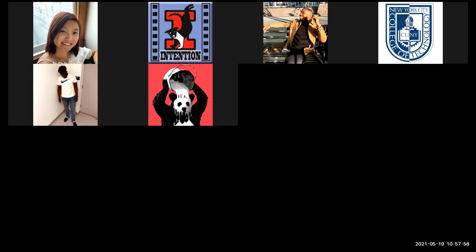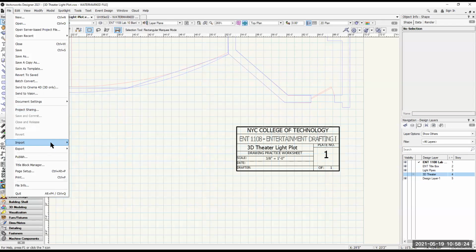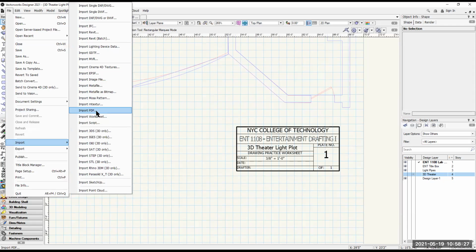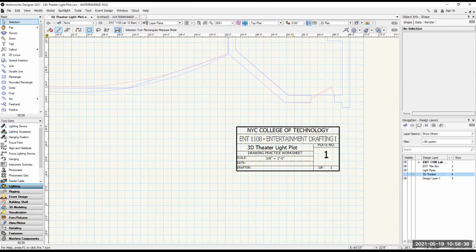The black box is a PDF, right? So I'm trying to insert that, but it's not working. Well, you have to import it. It's an import of the PDF. If you're going straight to Vectorworks, that's a different process. If you want to import a PDF in Vectorworks, that's file import. The PDF is down here because you could grab it right from there. My habit is I just tend to always go through AutoCAD first, but that's just pure habit. You don't have to.